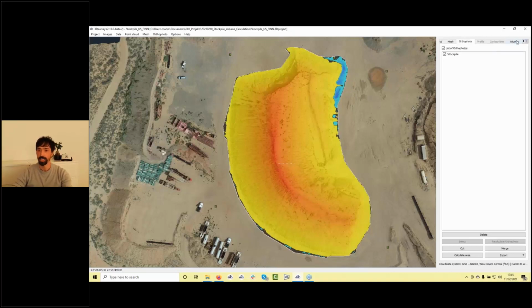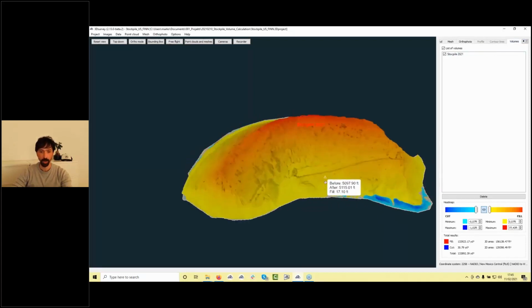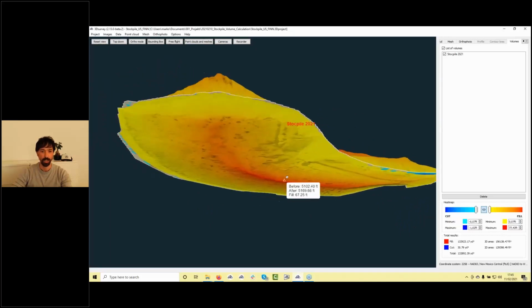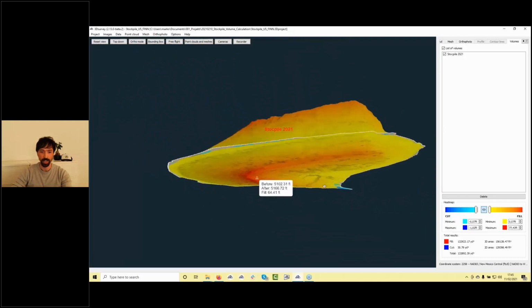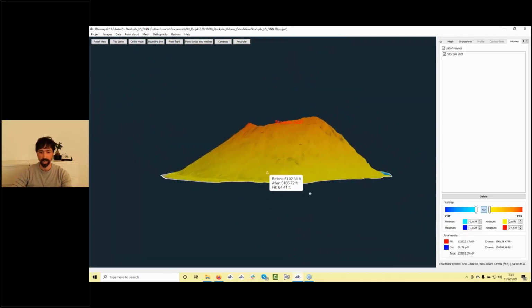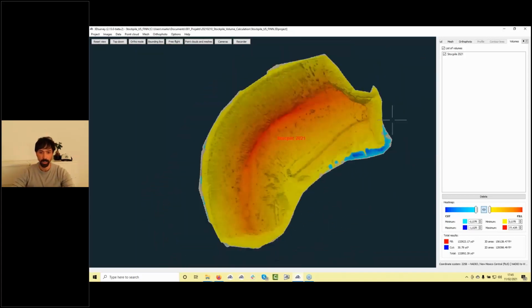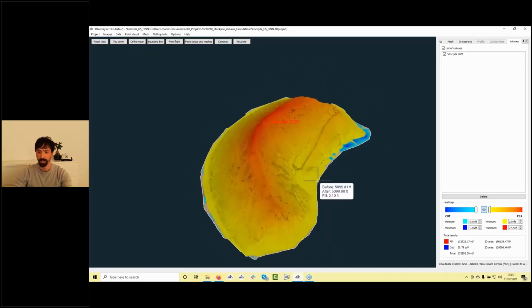You can additionally see this volume in a volume tab, which is optimized for volume visualization. So we can see now here clearly the surface below. We see it's nicely interpolated. It's not fully flat. So we actually look for the points around the model, around the selection, and try to create the smoothest surface. So this is really important. In this way we get the most accurate and reliable results.